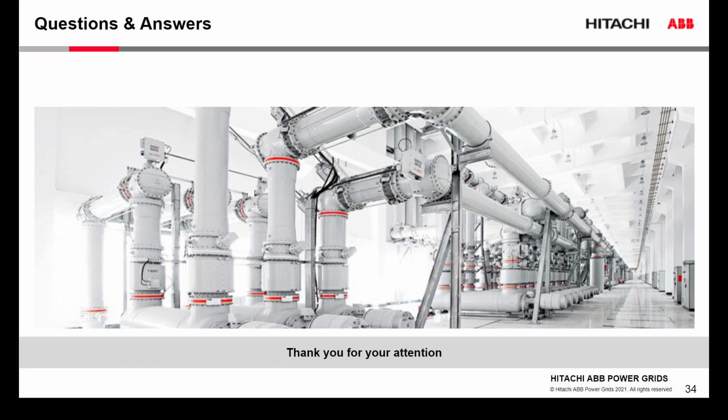All others are up to the customer, but my recommendation: that equipment is so small and does not require any architectural buildings. That building layout really does not add too much to the substation, but adds a lot to the reliability, and accessibility during bad weather conditions, allowing maintenance during such inclement weather. I would recommend indoor every day.